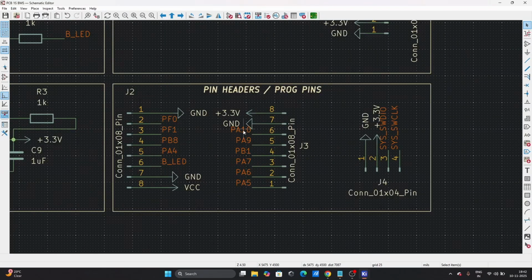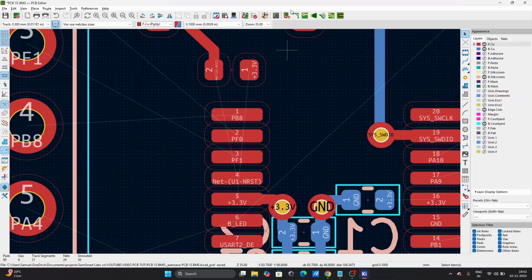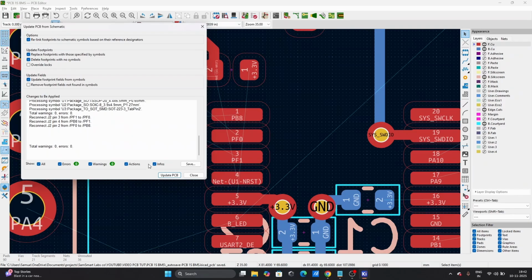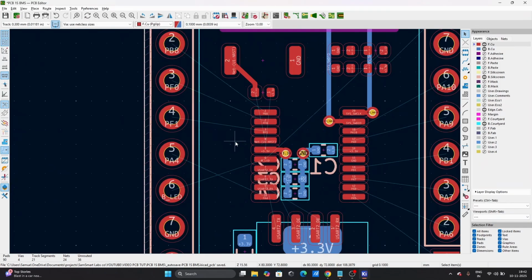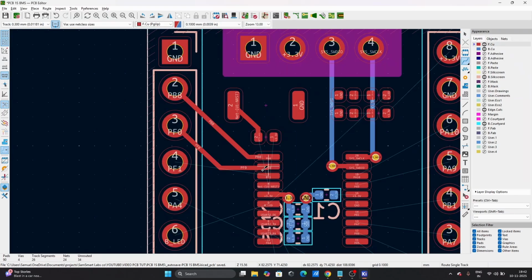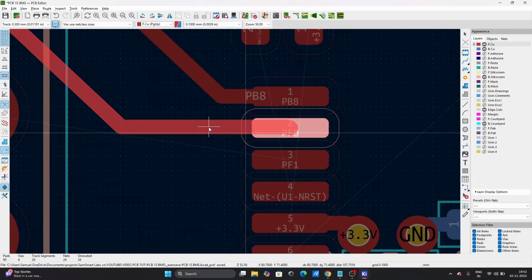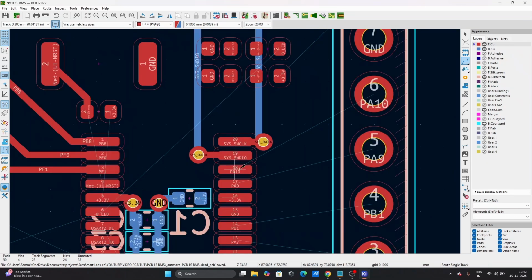Connectors. So I'll make this guy come. Let's swap these two, and I'll swap these two. Save it. Come here. Update. No, not here. Now it's perfect. So now I can just route this straight up like this. And do the same for these guys.